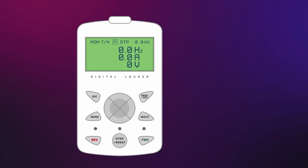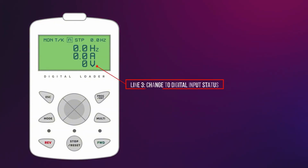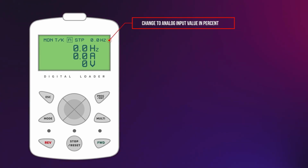Let's go through an example from the CNF menu together. In this example, we want to customize the inverter's keypad. On line 1, instead of frequency, we want it to display RPM. On line 3, instead of voltage, we want it to show the status of the digital inputs. And in this part of the keypad, we want it to display the value of the analog input voltage as a percentage. Let's go ahead and do the settings together.